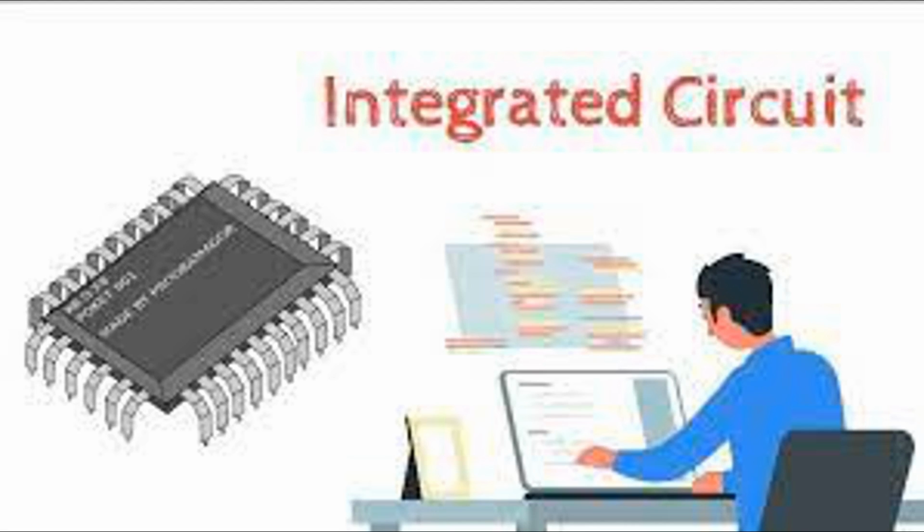Truth tables. Truth tables are used to define the behavior of combinational logic circuits. A truth table lists all possible combinations of input values and their corresponding output values for a specific circuit or logic function. Applications. Combinational logic is used in various applications, including arithmetic operations: addition, subtraction, multiplication, and division. Logical operations: AND, OR, NOT, XOR, etc. Data encoding and decoding.